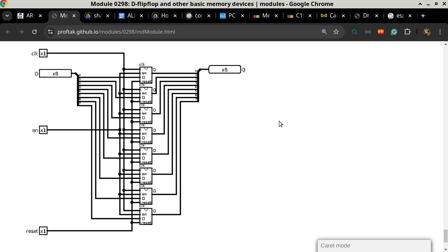So I'm building up this circuit step by step in this module. We started off with an SR latch, which is a memory device, but it doesn't even work like a real memory device. And then we moved into a level sensitive or gated D flip flop, which allows you to say, yes, I want you to remember the input. No, no, no, I don't want you to remember the input anymore. Okay, you can control it.